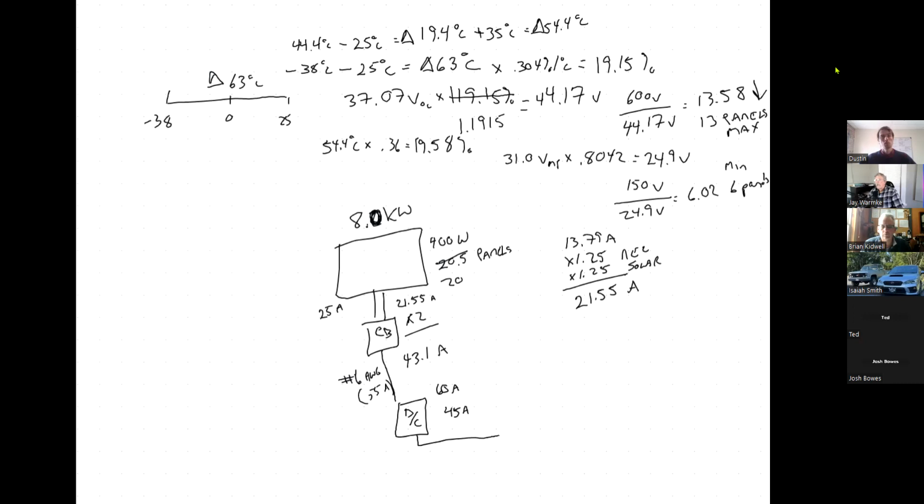It shouldn't. No, because it's just a disconnect, right? Yeah. So now the next piece of equipment that we're going to go to is the inverter. For a grid tied system, it's going to be an inverter. We've already decided that the inverter we're getting is an 8.6 kW inverter, right? Mhm. The wire here is also number 6.